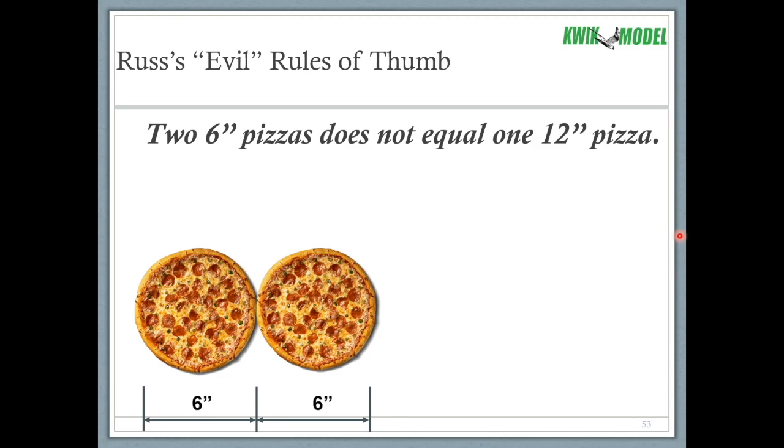I was not too concerned about the insulation being compressed in a couple spots, and I knew that I was asking for a lot as it was, so I just said very clearly I need a 12-inch chase. Well, what happens? I get a call from the installer, and he says, hey, your design is all messed up. You call for a 12-inch duct coming down here, but there's not room for it. And I said, well, what happened? I called out for a 12-inch chase.